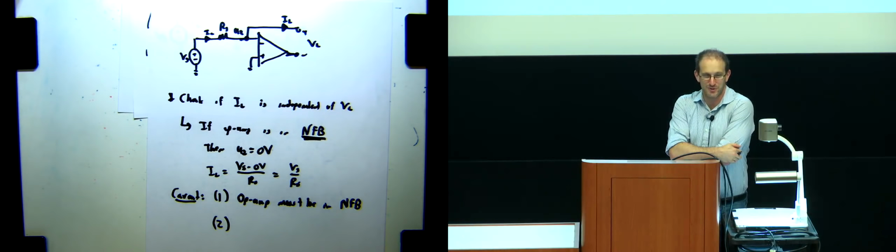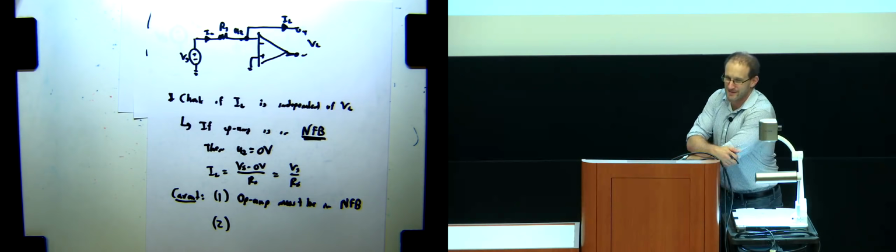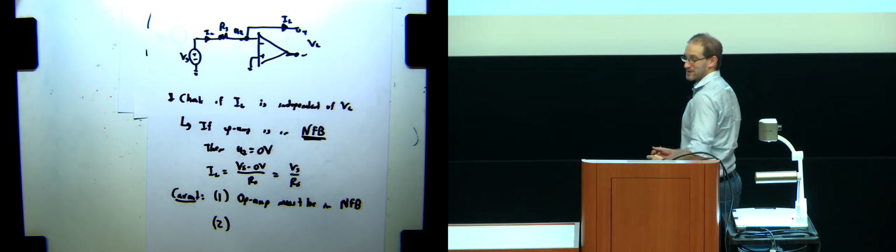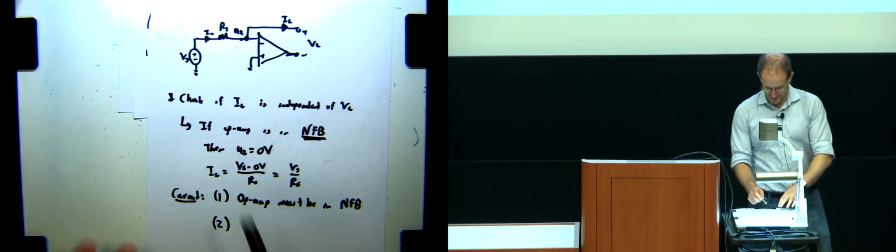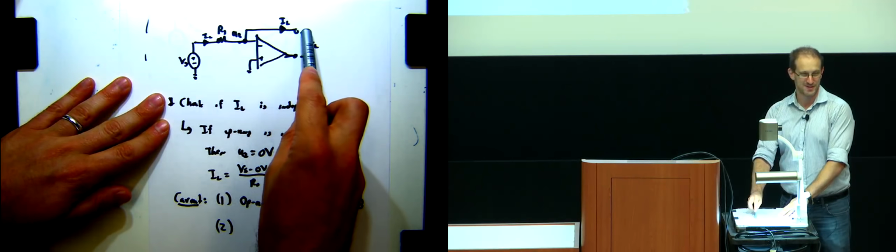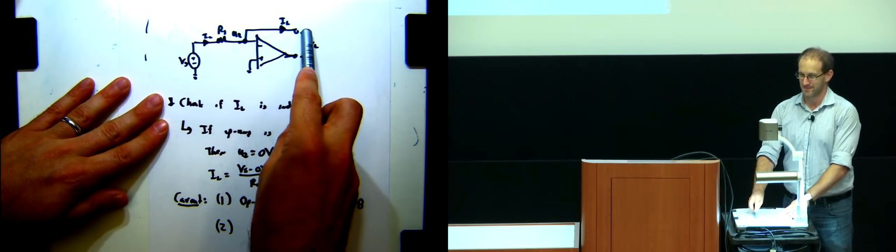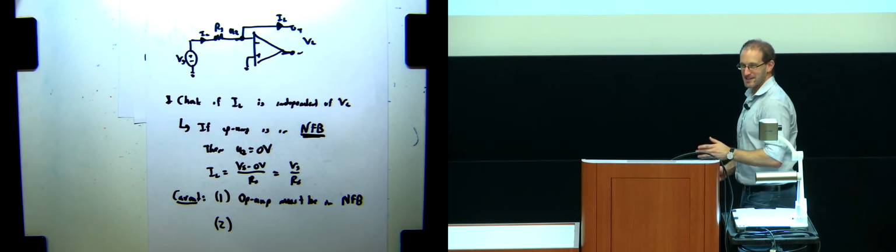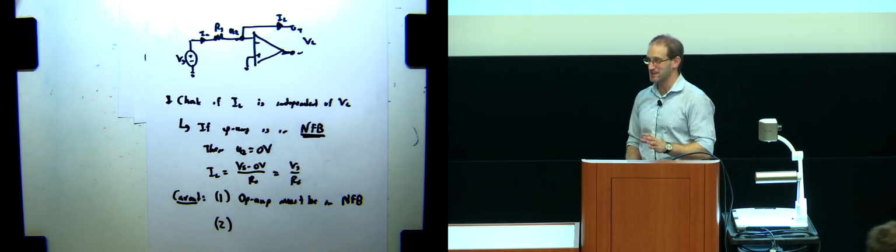Let me give you guys a hint. Look at U2 and look at how it's connected relative to the output. So what did we say is the value of U2 when we actually hook this whole thing up? Yeah, it's 0 volts, right? So if U2 is 0 volts, that means that over here, this also had better be 0 volts. That may not seem like it's all that important, but trust me, it's going to matter.